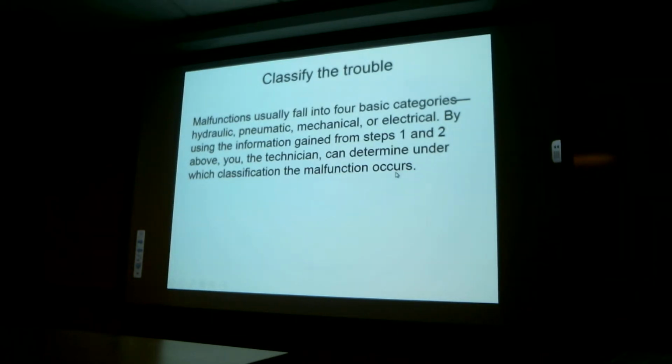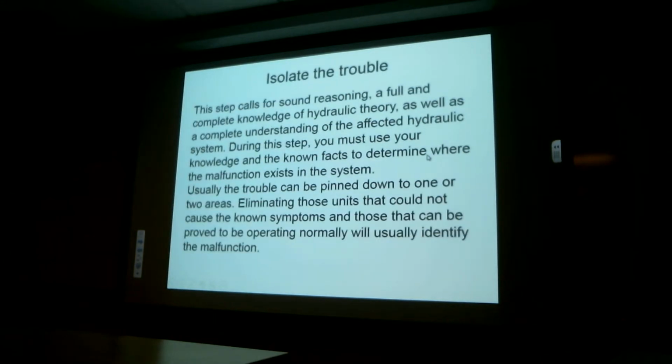So now you're classifying it, you're further working your way down through a trouble tree in order to figure out what's wrong. Oh, by the way, a lot of manufacturers use trouble trees for troubleshooting. That's a very difficult, laborious task to actually create one. I work with some very skilled and talented people at Sikorsky that did a pretty good job developing trouble trees. You have to have a basic idea of what's most probable, in order of importance, that might potentially fail to work on a trouble tree and get one into a service manual.